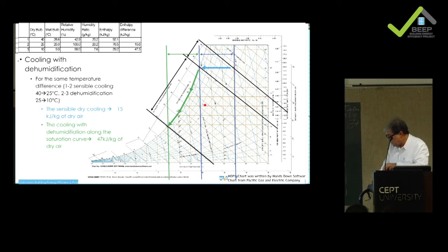If we could have chilled water in the range, if you make, for instance, radiant cooling, suppose, and you only dehumidify the air with what Rajan was talking about, the treated fresh air dedicated outdoor air unit, you can imagine that instead of going down to this level, you could have water maybe at 16, 18 degrees for radiant panels. So you would already remove this only for the fresh air a little bit, you would use it. And that means you could significantly reduce the cooling load for the same cooling power, but simply not avoiding latent.